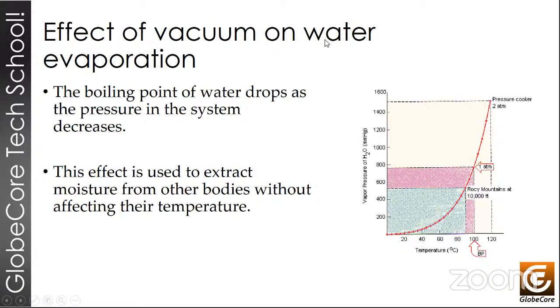There is no chemistry involved. It does not depend on any consumables, such as absorbents, and it's completely tied to the physical properties of water, and this is it. So it's important to assure that the oil remains under vacuum for as long as we can arrange that, and that the surface area of that oil is the largest that we can achieve. That will extend the drying process, and it will also allow us to degas the oil, which is another added bonus of the process. Next slide, please.